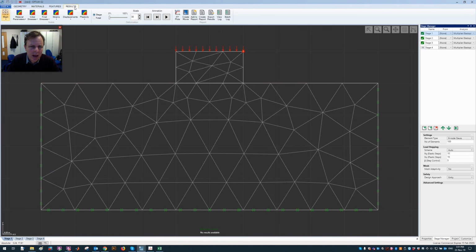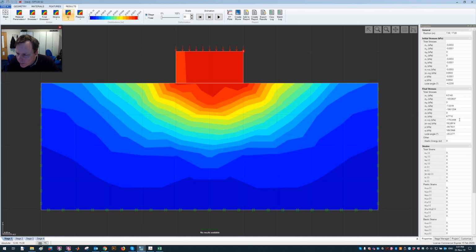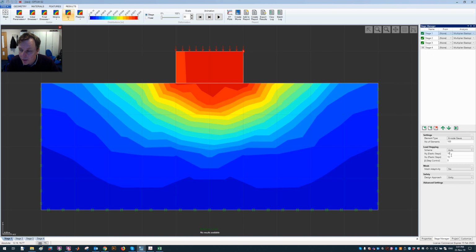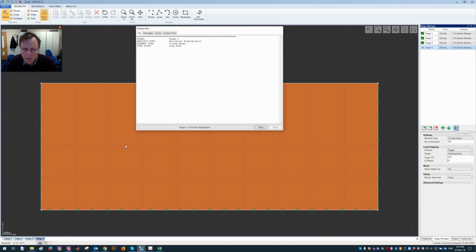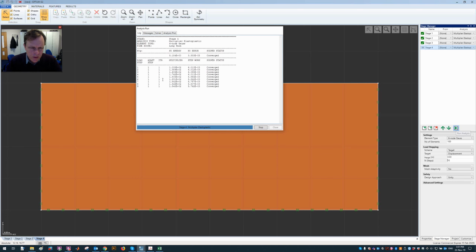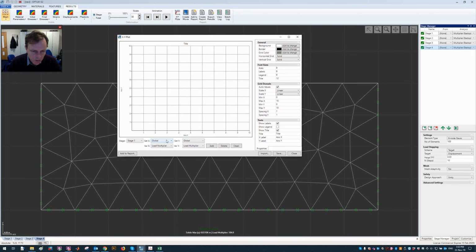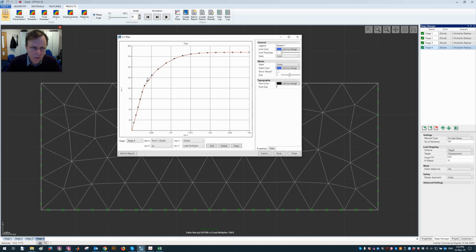And if we look at what we had before, we had a displacement, it's the absolute displacement up here at this point of 0.03. And we did that in 20 steps, right? 10 elastic and 10 plastic. So let's now try to do the same in 10 steps, 0.03. This is often more convenient, but you have to have some idea of what displacement, of course, you want to take your system to. But let's just plot the first one, the auto again, with 20 load steps, and then this one with a target load step and with a target displacement, but only 10 steps. And of course, this one is a little more crude, a little more coarse than the one with 20 steps. You can change that to 20, and then you will have pretty much the same.